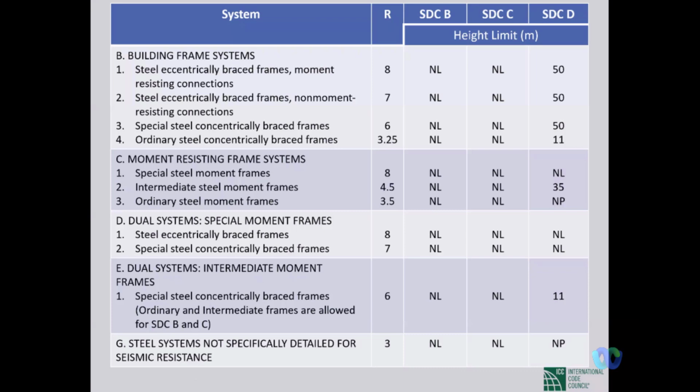Even for zone 4, zone 3, seismic zone 3 of Bangladesh, if the soil is not rock-like, even for stiff soil, we have to design structures complying with SDC D. And for seismic zone 2, if the soil condition is not good, if it is not firm or stiff, then we have to design the structure complying with SDC D.